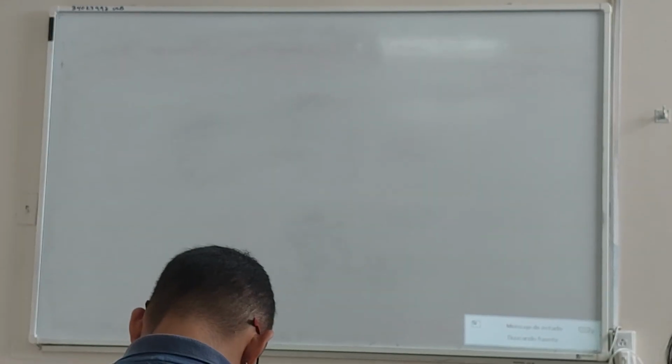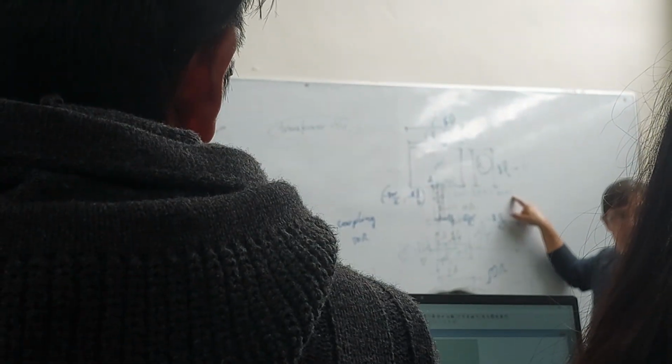Then, in the calculator of the software, the width of the transmission line is 3.051 millimeters. Then we have to define exactly a transmission line with this width.